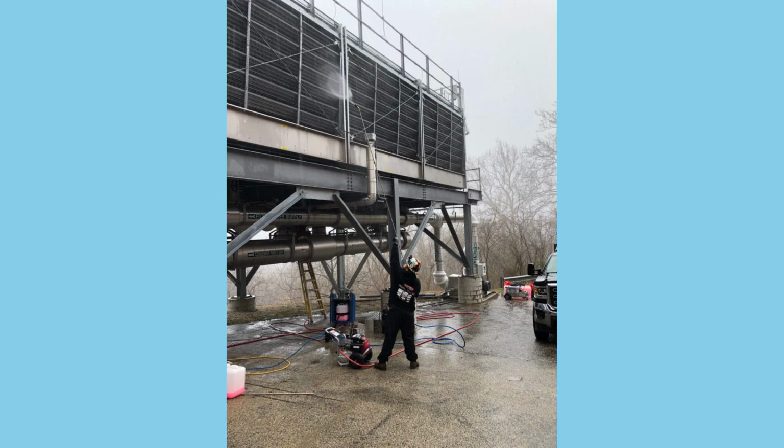Maintenance, reliability, and operational practices. Reliable operation depends on disciplined maintenance. Clean condenser and evaporator tubes annually. Maintain chemical water treatment. Inspect pumps, seals, and strainers based on manufacturer's recommendation. Verify sensor calibration and VFD set points. Review chiller trend logs monthly for anomalies. Preventive maintenance preserves efficiency, extends equipment life, and reduces emergency calls. Even small neglect, like dirty strainers, can raise pump energy by 10–15%.